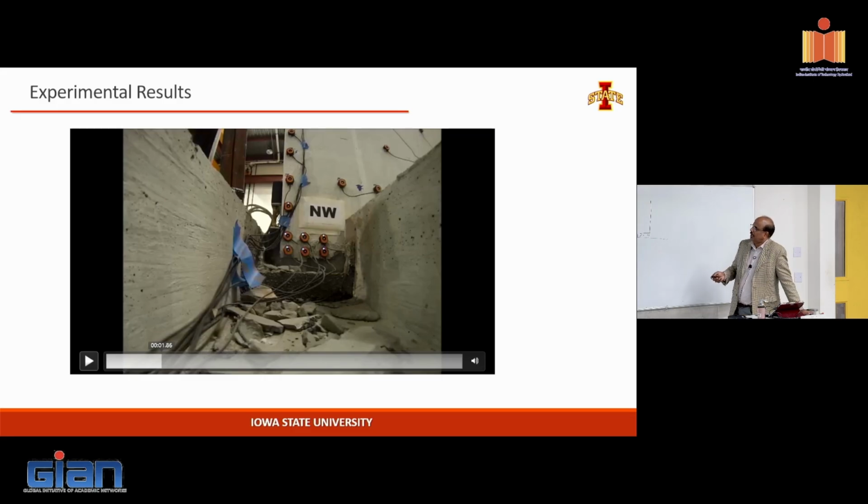of the wall. You see some concrete got spalled off, so those are cover concrete basically. Every time it hits, there's spalled off cover concrete. It doesn't compromise the actual core of the structure. So this is what people were trying to prevent by putting steel armor, so that when it hit, it doesn't spall off the concrete. What we figured out was that when you establish a contact with the grout pad, so